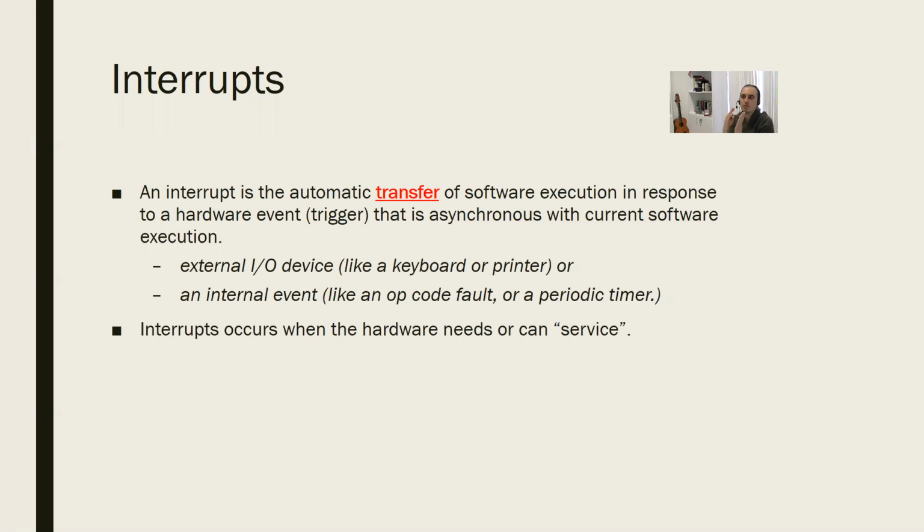You just give it a code, it runs a sequential code, pumps water, waits for 20 seconds, waits for the pump to conclude. A sensor outputs something, it waits busily for the sensor. When the water is pumped, it continues. So it's a sequential operation. However, your cell phone can do multiple tasks simultaneously. The mechanism for this is called interrupt.